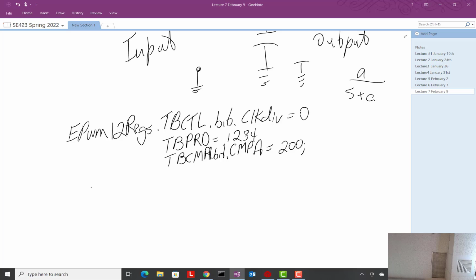And so that's why you have to write to it. So that's part of it, right? You've got to tell it to wake up. You've got to tell it to do something. For example, if you're not using a peripheral, you shouldn't clock that peripheral because it wastes power, doesn't it? So one of the first things this processor does is turn on the peripherals it needs. And that's also in your source code.